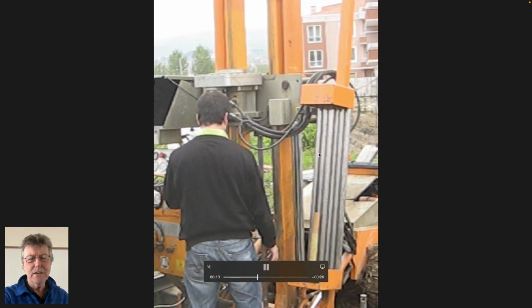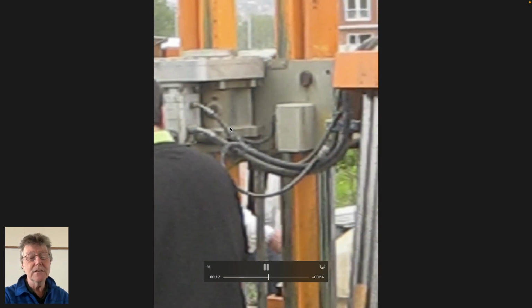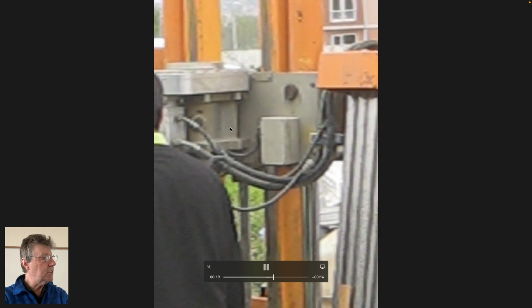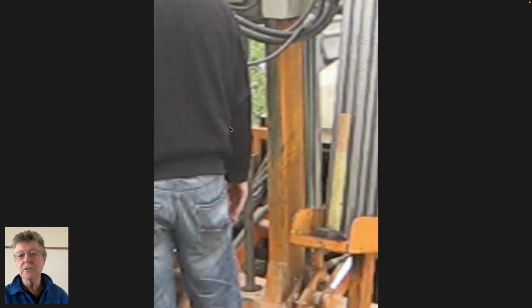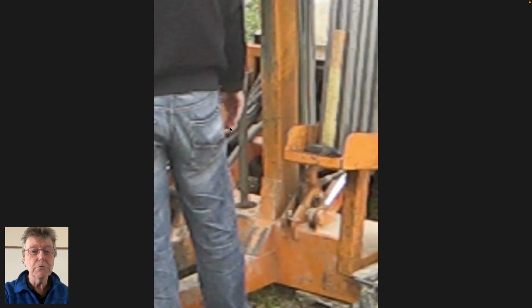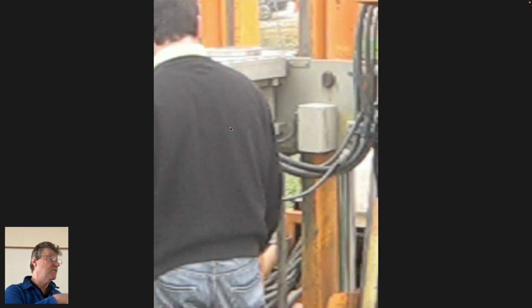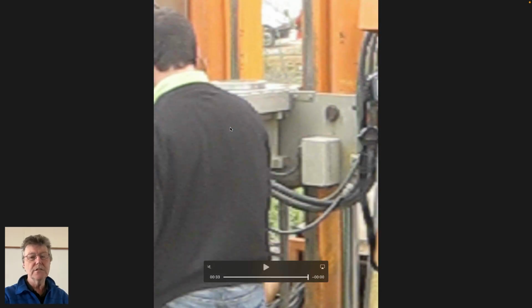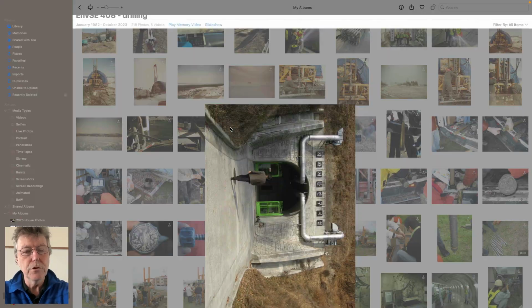They come out, I guess they're all threaded on the ground, and then you take the digitally acquired pressures, tip resistance, and end bearing, and then use that to say something about the subsurface. For your interest, it would be permeability distributions with depth, but you can also use the other metrics to be able to say something like whether it's a clay or a sand or a silt. And obviously you can't use it in rock. We looked at all these.